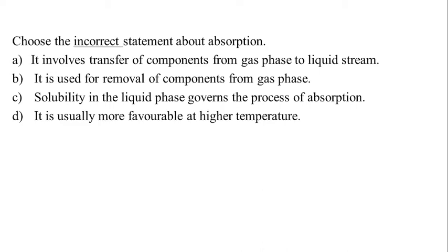Flooded condenser. Okay, fine. A flooded condenser means definitely it's a condenser subcooler. Most of the time you will find that it's a horizontal heat exchanger in which some of the tubes remain submerged in the liquid which condenses.